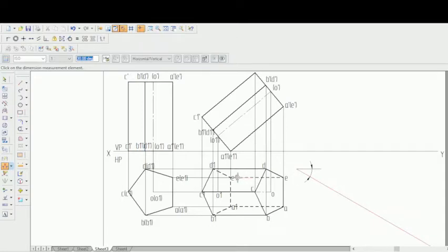So let's move from any one of the corners of that edge, either from E1 or the other corner. Let's first move it and place it here, then let's rotate it. I'll move it from E1 and first place it here. Then using the rotate option, let me fix this E1 point and rotate from E1 to overlap on this. So first you will have to select this.